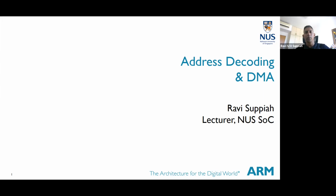Though we are used to using ready-made development boards, at some point you may have a task to design your own embedded board, at least from the processor level up. So you need to wire up your processor to memory, to IO devices and so on, and you need to have this concept clear: how do I map various peripherals to different parts of my address space?